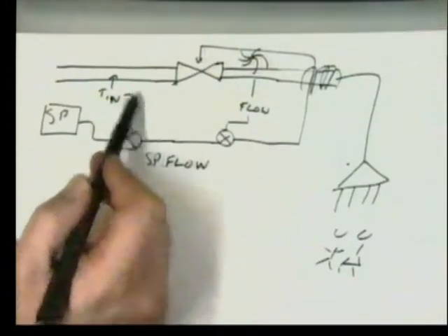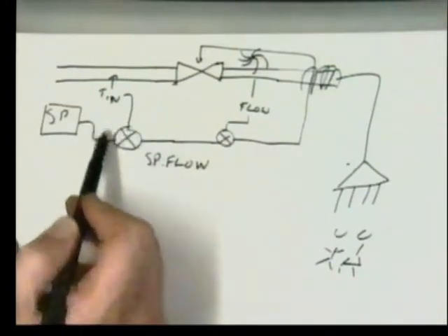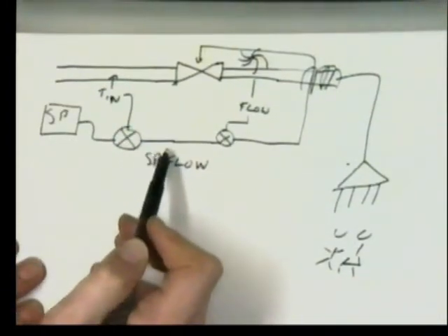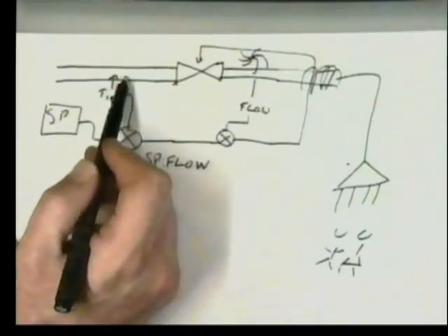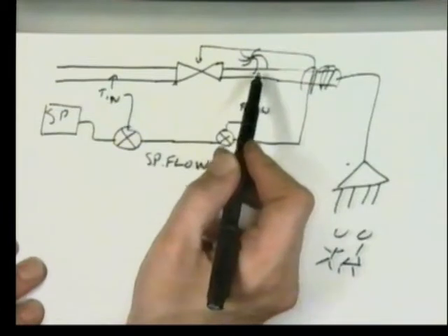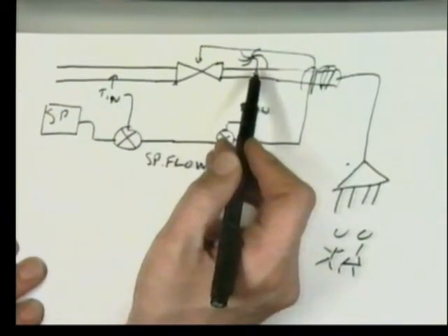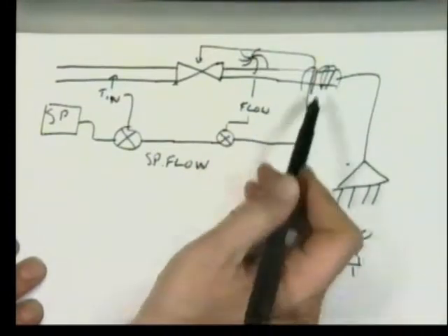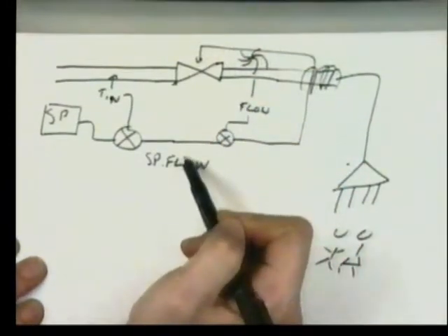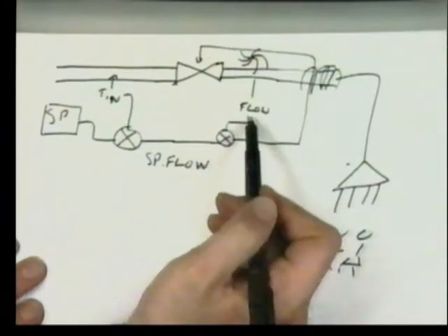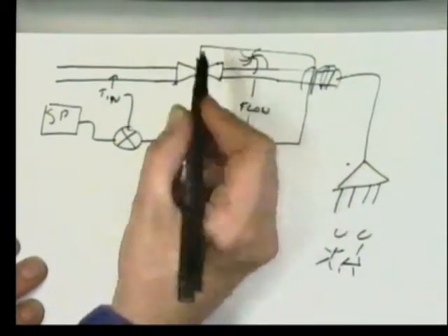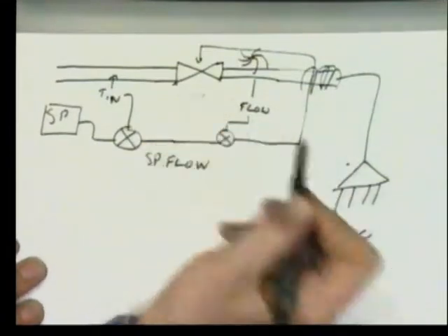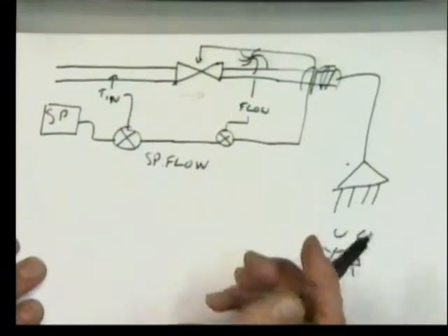It was combined feed-forward control to predict the flow rate we needed to get the correct set point based on the current temperature of the water. Then we used a turbine meter to measure the true flow rate, and we had feedback control based on the calculated set point and the actual measured flow rate that controlled the valve, and so we controlled the amount of water that flowed in the system.